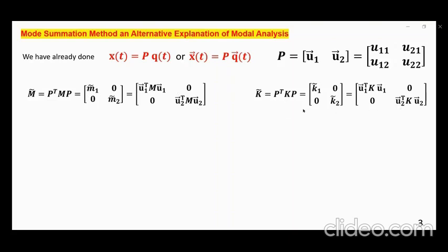Now, the same thing is going to happen with the stiffness matrix. The good thing is that the stiffness matrix, which may not have been diagonal, through this transformation always becomes a diagonal matrix. I put tildes here to remind you that this is not the same as K1 that you had for the original system, and this is not the same K2. These are, in fact, these values.